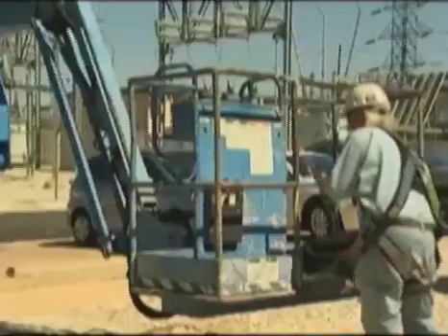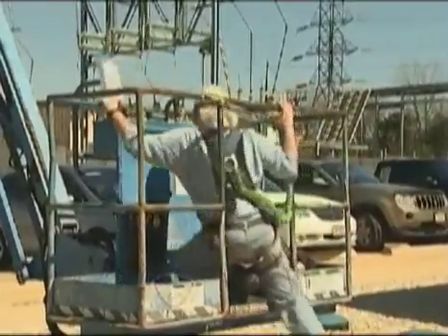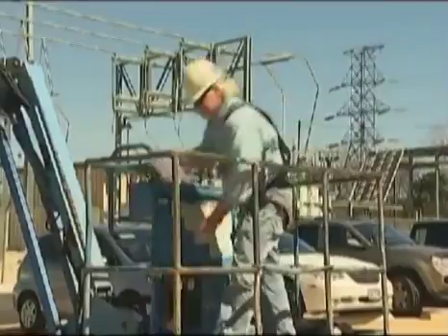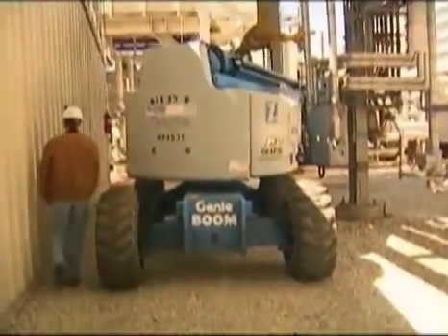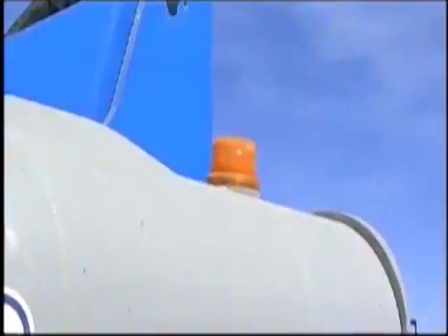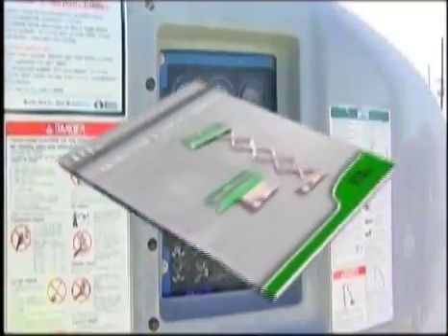There are 2 main inspections that must be done when using an aerial lift device. A pre-start operation inspection of the lift must be performed before each use, and an inspection of the surrounding worksite in which the lift will be utilized. The pre-start inspection includes a list of items that should be inspected before use. The manufacturer provides much of this information in the operator's manual.